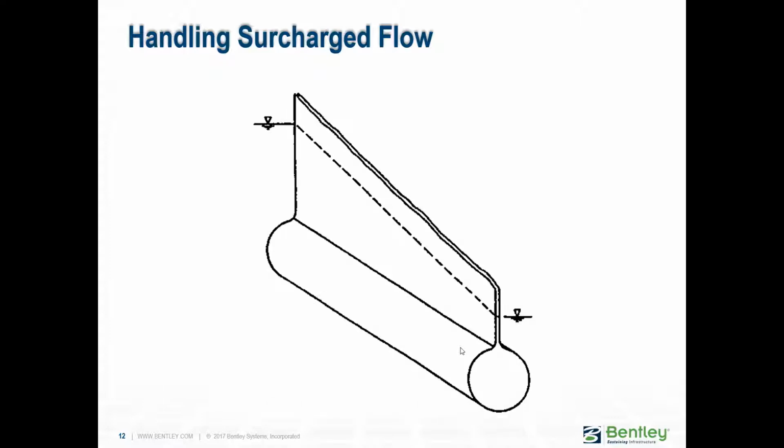So this is how we model surcharging or full pipe flows. We assume that a pipe has an invisible Preissmann slot, is what it's called, and that way the volume of water there is negligible because this would be like 1 millimeter wide, and the idea there is that we can create a continuity with the water level.